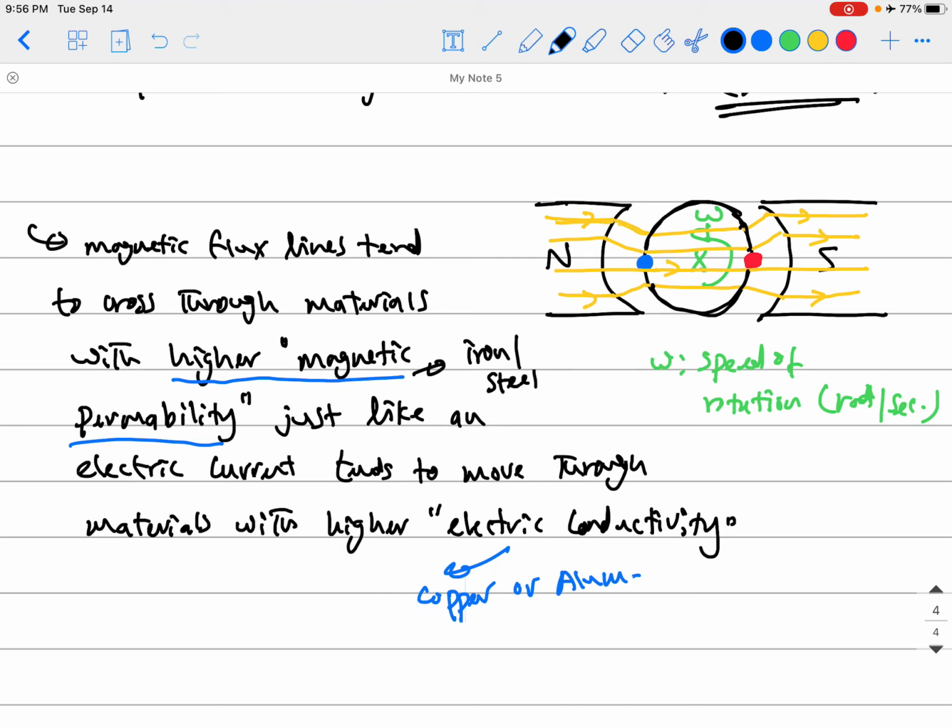If you don't have this cylinder inside, made of iron or steel, you will not have a uniform shape magnetic field like this. And with a more uniform magnetic field, you can direct the field to the spot you want inside the machine. And we are directing it into the coil, because the more magnetic field cutting this coil, the more energy conversion happens. So we need to do this.